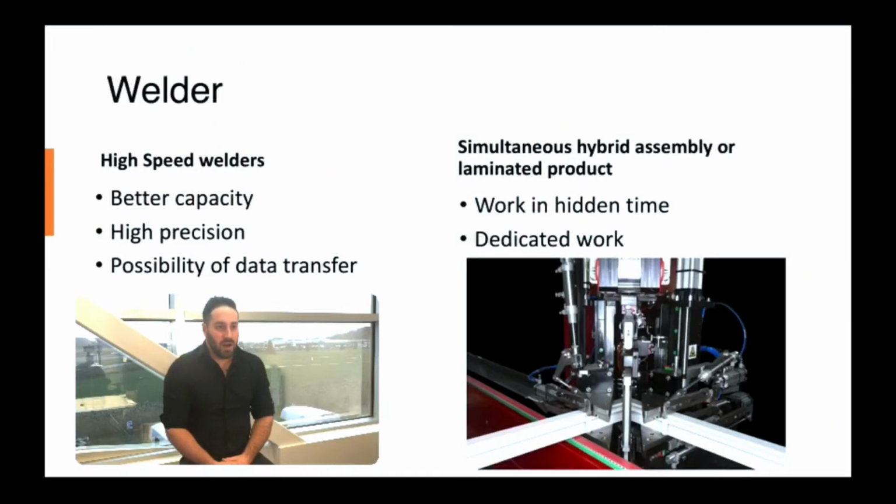If now we're talking about different types of welder, if you build a hybrid window or you're using laminated PVC, there is a lot of new technologies around the seamless welders that are out there. It's not necessarily a technology that has been well adapted to the North American window just yet, as the walls of our windows are much thinner than what we see in Europe. But I have seen those work with hybrid windows and laminated windows. They work very well, but at the same time, it's a long cycle.